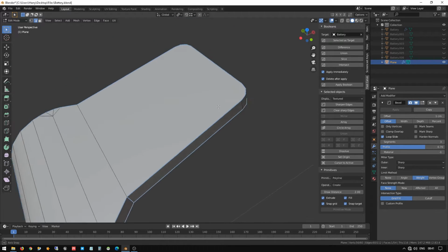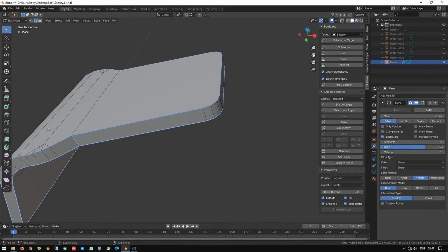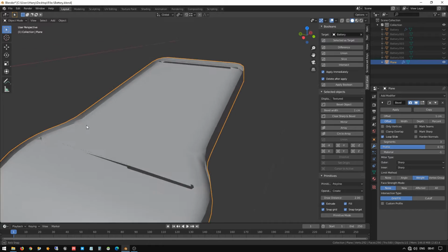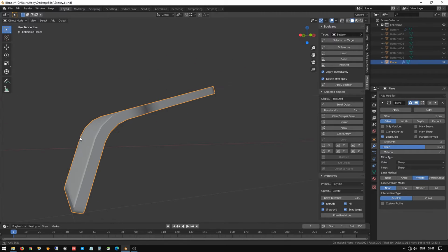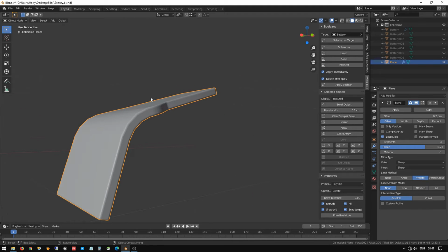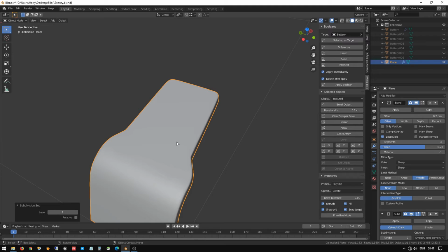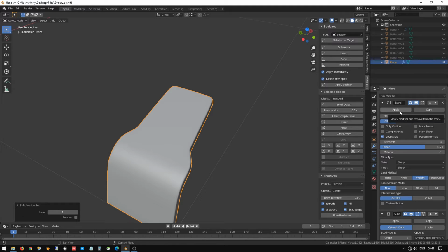What we are going to do for this is, here you can see one length angle is not happening properly, so that's why that bevel option is not working fine. So we can reduce that bevel option to 0.2. Now we can see it's beveled correctly. After that press Control 1 to smooth the modifier, so you can see it's cut nicely.